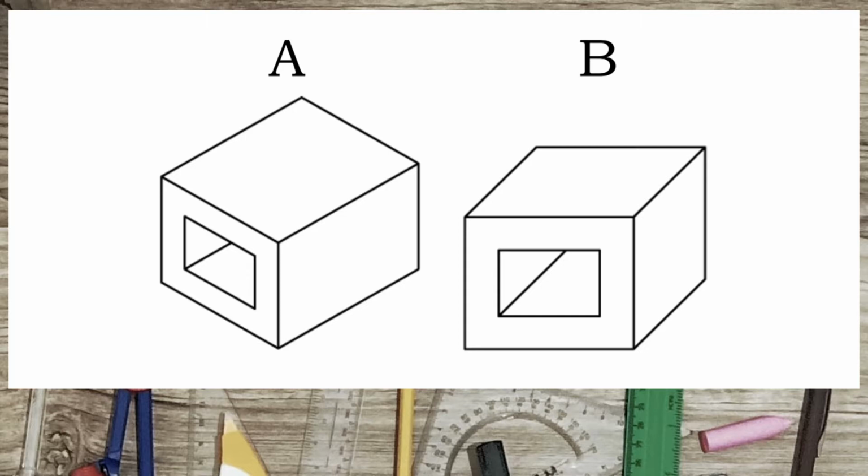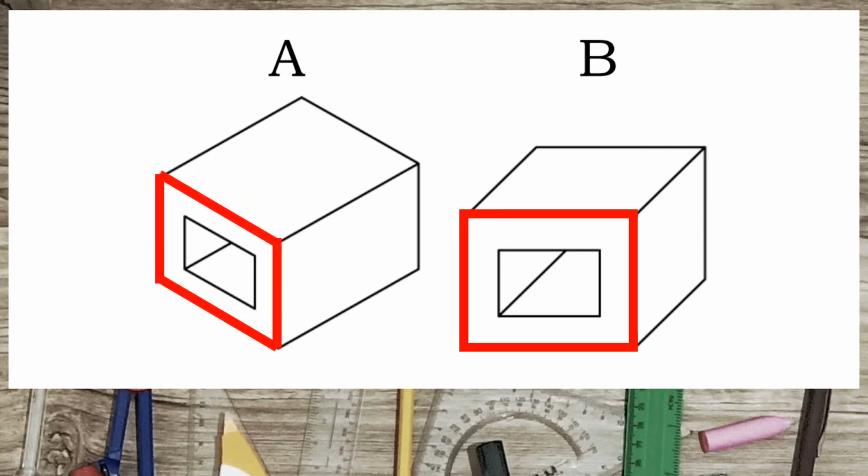As I have said earlier, in an oblique projection, one of its surface is parallel to the plane of projection. It means it's like you are looking directly to the object's surface, so just like this. While in an isometric projection, its surfaces are tilted at a specific angle. Its sides are projected at 30 degrees. In this example, we can clearly see the difference, right? Both front views are highlighted with color red to emphasize the difference on how they are projected or drawn.